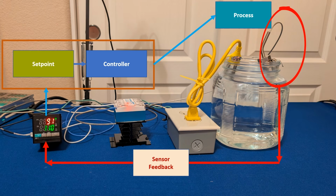So the system is constantly measuring, comparing, and correcting. And that continuous cycle is what we call a feedback loop. In this example, our set point is 110 degrees Fahrenheit. Now we know how the feedback loop works. But the real question is, how does the controller know how much heat to add? That's exactly what PID control determines.